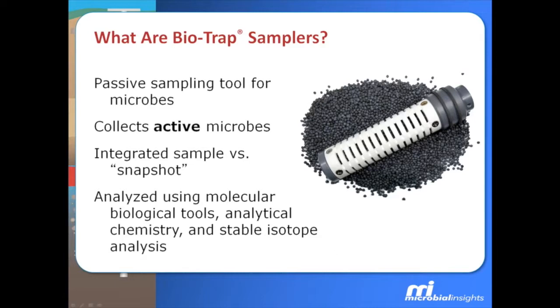For those of you that may not be familiar with biotraps, they are a passive sampling tool, a passive sampling tool for microorganisms. And by passive, what I mean is that you install a biotrap in an environment to be sampled, and you basically leave it there to allow biofilms to be established inside the medium of the biotrap, which is the biosep beads that you see in the picture here, that I'll tell you more about in just a few moments. But you leave that in place typically 30 to 45 days, and then you retrieve the biotrap for analysis. So basically there's no care and feeding during the incubation time.